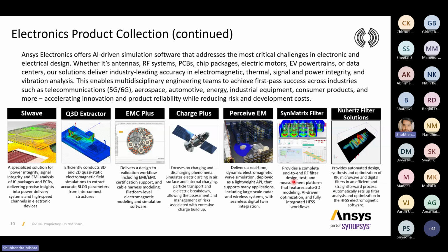Then we have SIwave. SIwave is a dedicated tool for PCB analysis, from signal integrity, power integrity, EMI, EMC, anything you want to do, you can do with SIwave. From the basic layout import to radiated emission and conducted emission, you can do anything at the PCB level. For system level, we have HFSS. Q3D is there for RLGC parameter extraction, where you can extract those RLGC parameters to proceed with the PCB simulations.